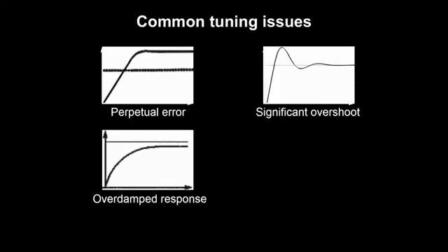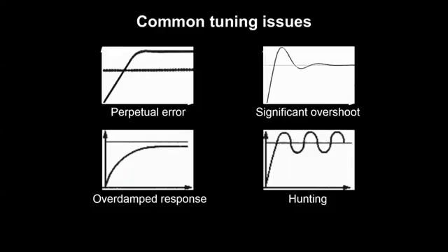We can have a quicker control loop, but maybe now we're overshooting a little bit. And in systems where we're susceptible to, say, high pressure or temperature changes, like within a duct, that may become an issue. We may damage equipment. And we may have what's called hunting or cycling. If you can ever imagine looking at something like an economizer damper, where it appears that damper is just closing, opening, and by the time it realizes it's overshot one end of the set point, it's shooting back to the other one, we would call that hunting, and that's something that tuning can address.